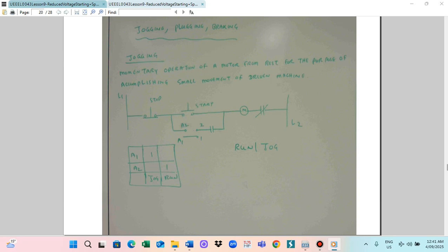So this circuit is off. This circuit off means the motor can only run when you press the start switch. This is why we use the starting and the jogging. Jogging and the run are in this control circuit. This one we can also integrate into the full starter circuit. So this is a run and jog function, and we can integrate it into the full starter circuit.